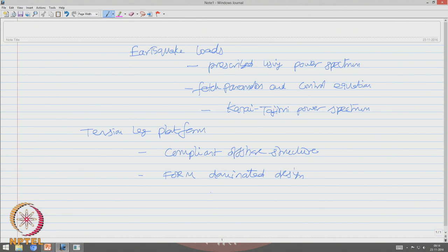In the sense, as per the design, the buoyancy force exceeds the weight of the platform and that is equated with the tension in tendons with the platform to equalize the buoyancy. So, I have a top side with all details, which we say the flare boom, the crane, the living quarters and the drilling derrick, which is now assembled with a column member and a pontoon member.